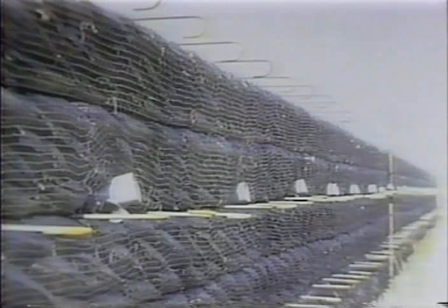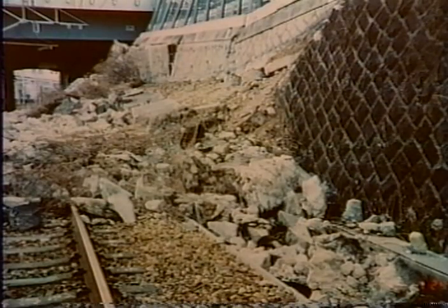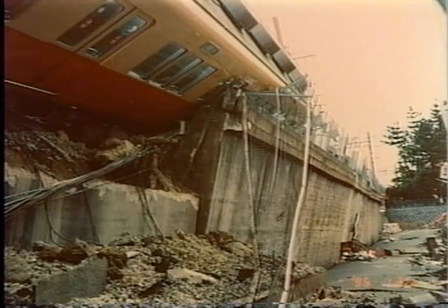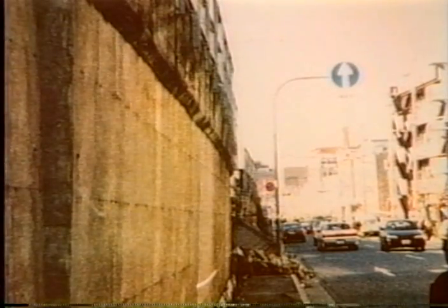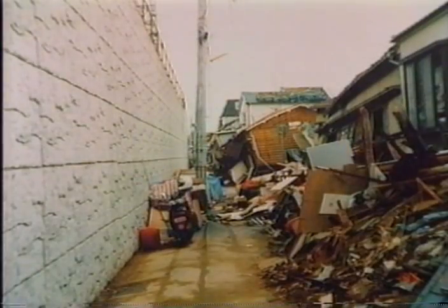Geosynthetic reinforced walls are flexible, which makes them attractive for earthquake zones. During the Great Kobe earthquake of January 1995, many conventional masonry and reinforced concrete gravity-type retaining walls totally collapsed. Many modern cantilever reinforced concrete walls were also seriously damaged by excessive tilting. Geogrid reinforced walls with full-height concrete facing performed well despite the devastation around them.